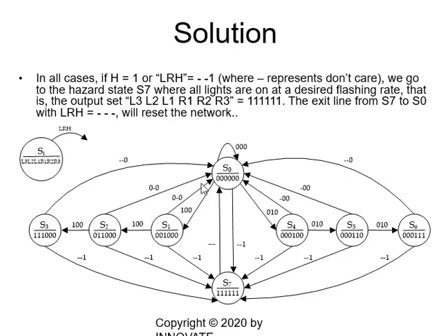Now the same thing with the right pattern, similarly on the right side. If the right signal is on, we have 0, 1, 0 and the light will be light 1, then lights 1 and 2, then lights 1, 2, and 3. Once we are at S6 with hazard still 0, we go to S0, and the cycle repeats itself to give the beautiful pattern of 1 light, 2 lights, and 3 lights continuously until the right turn is removed. Once the right turn is removed, we go definitely to S0.